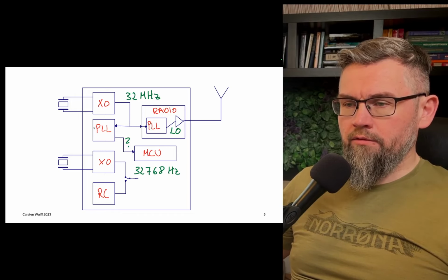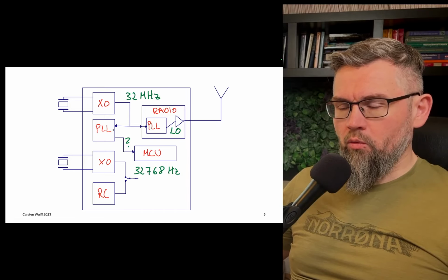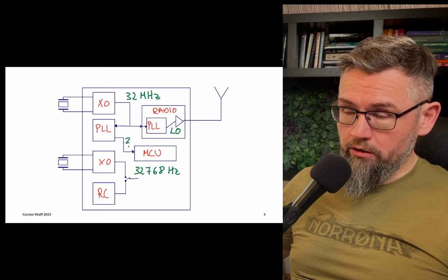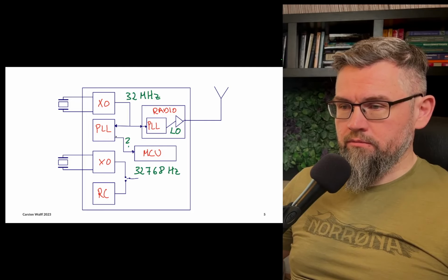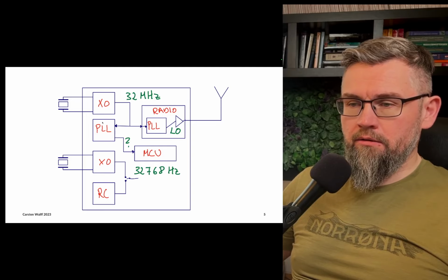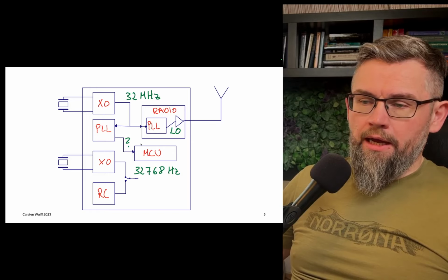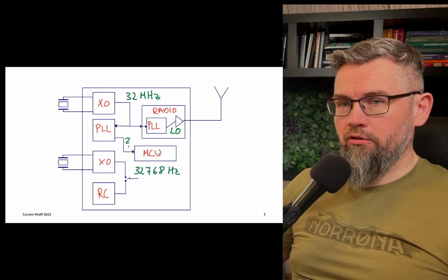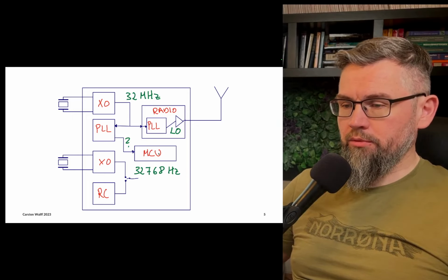And then we have what we call phase-locked loops. So they are a type of block which can generate, well, it could generate the same frequency, 32 megahertz, or we can generate any different one. And we'll look more into that later. And there will be PLLs in the system, there'll be probably a PLL in the radio, and that allows us to, for example, run the microcontroller at whatever frequency we choose for that particular chip.